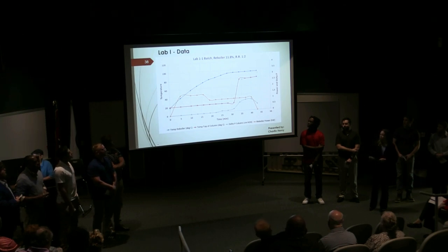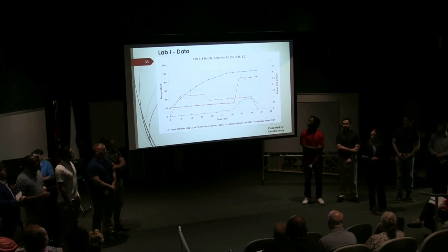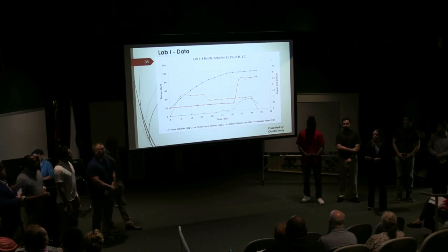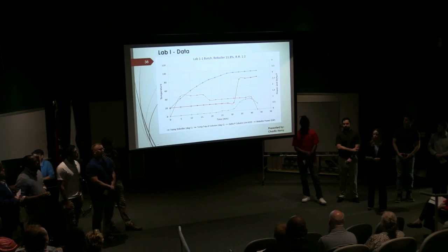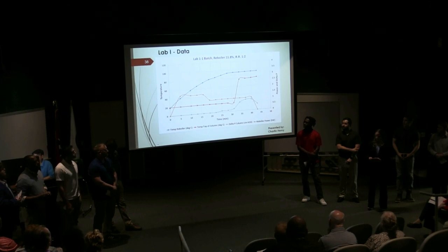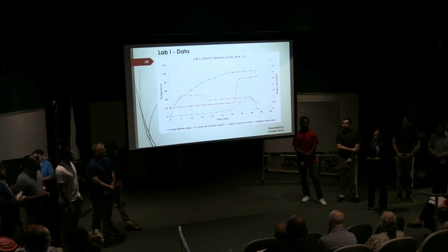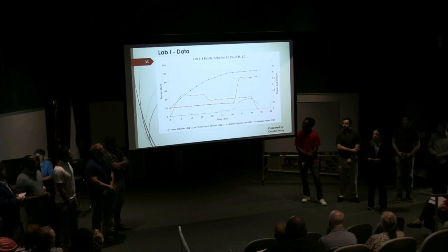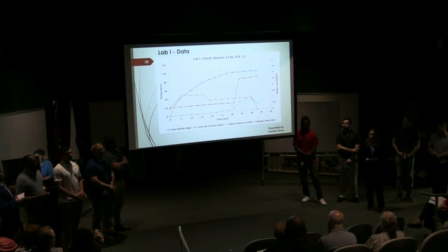Our top of the column temperature, we collected product for less than 15 minutes and the temperature couldn't be kept stable. It increased rapidly, going up 2.5 degrees. We truncated the run because we decided that adjusting the reboiler power wouldn't be effective. Our delta P curve, a higher pressure drop means a higher flow rate, and this is where we expected to see our highest production rate. In summary, this wasn't a stable run and it was the lowest reflux ratio that we ran.